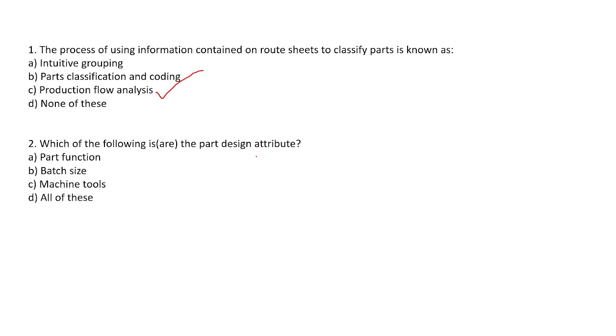One is the traditional process layout, and one is the cellular layout. In the traditional process layout, there is similarity in the machines, like drilling, milling, and turning. We can classify based on this similarity in machines and then make a process layout. In the cellular layout, each cell specializes in producing one or a limited number of part families. Likewise, we can make a layout of the group technology.